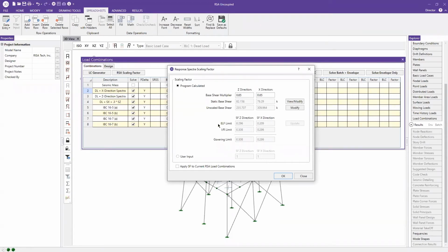And then the other limit that ASCE 7 requires is that once you get your RSA design force, it cannot be lower than your equivalent lateral force method force. Meaning that if, for instance, using the RSA I've got maybe, in this case, 233 times whatever the R is, and the force is smaller than my ELF method, then I have to bring it up to the ELF method. So in RISA, we are comparing these two factors, and then we are using the larger one of these two to get your scaling factor.